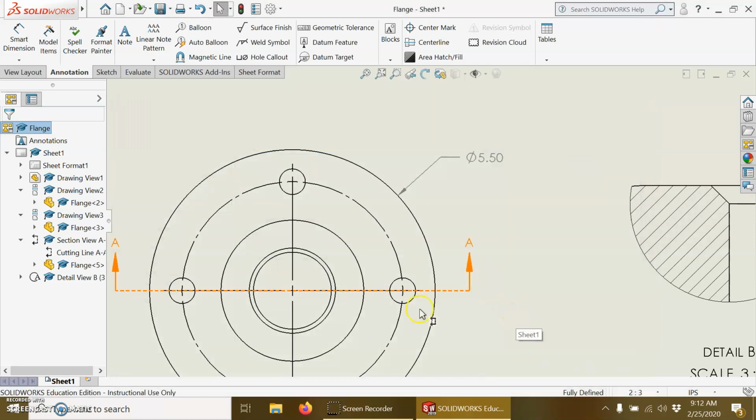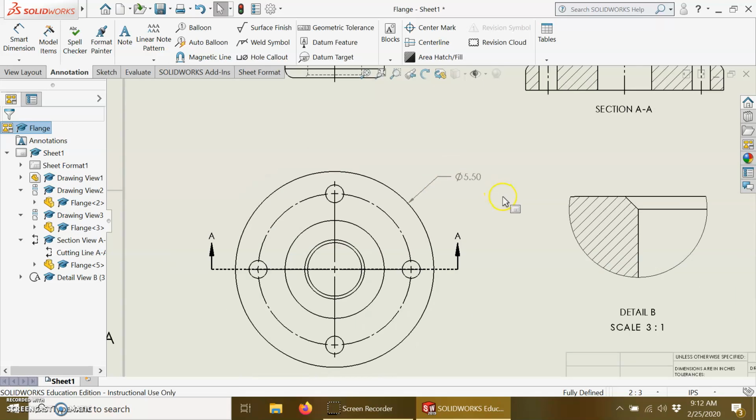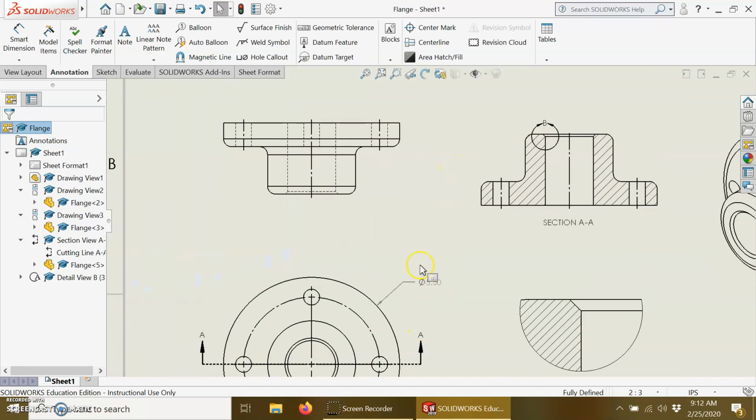And so now you see the leader line is bent, so the diametric dimension is shown horizontally, which is more typical of what we see in the United States. It still tells us that the outside diameter is there. You can see that little circle with the slash through it. That's the diametric symbol, which means we're talking about a round part.